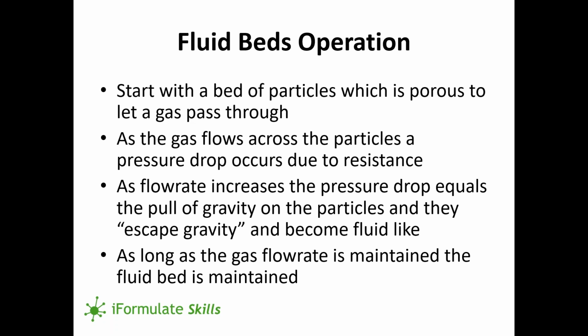One of the differences is that spray dryers are limited in time, as Jim mentioned, because you basically have a droplet which falls under gravity from the top of the tower down to the bottom. So there's a time limitation. And you can see when I describe fluid beds that the time limitation disappears with fluid beds. So that's a difference between the two.